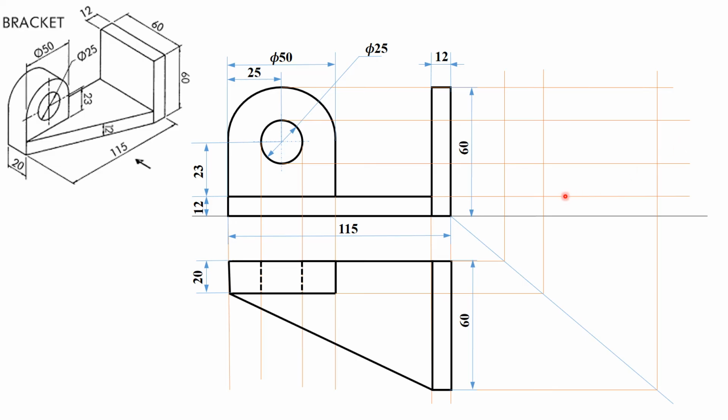Now within these projected lines I'll be plotting my left side view. Let us see. First, let us go for this surface which will look like a rectangle here. This will be the height, and this is how your views will look, yes or no? From the bottom to the top, this total height will be 60, which is equal to this height. Alright, next we'll see this surface.